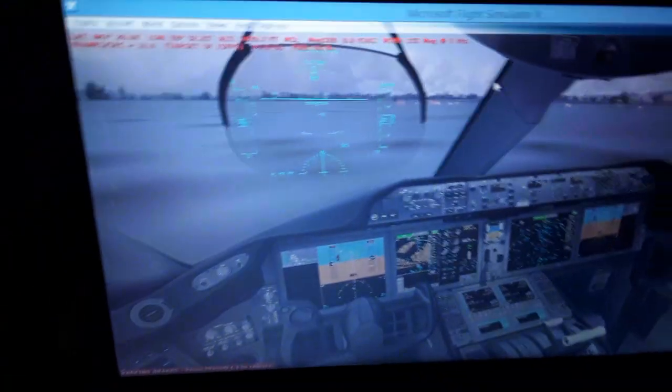So we have also the navigation display. The navigation display shows the GPS position of the aircraft, the magnetic north pole, the geographic north pole, and the magnetic variation depending on where we are in the world. We have the terrain and weather reflections from the weather radar. You can see the terrain around you and below you, displayed with red, green, and yellow amber color indication. Also, the lakes, the rivers, and the sea are displayed in blue. We have the airports where they are located, our own airport, other airports with a 4-letter code name, the runways we're going to use for takeoff and landing, the taxiways, and also the airport maps.